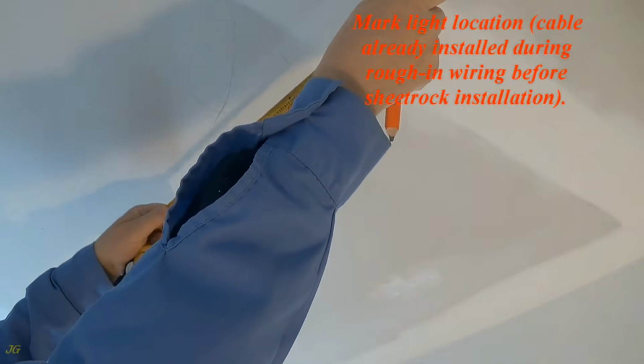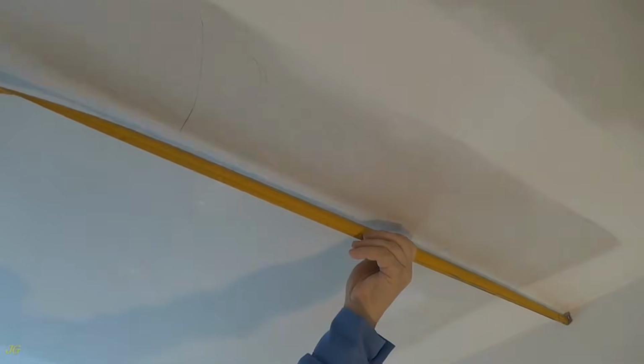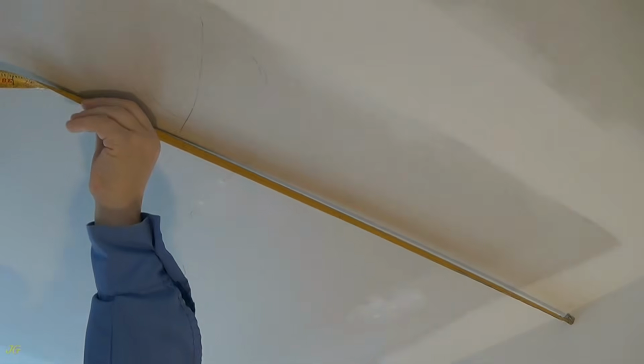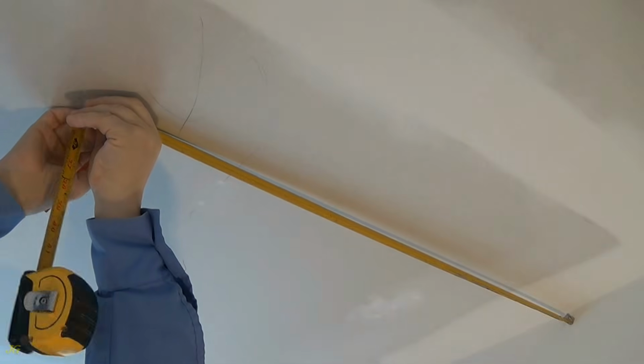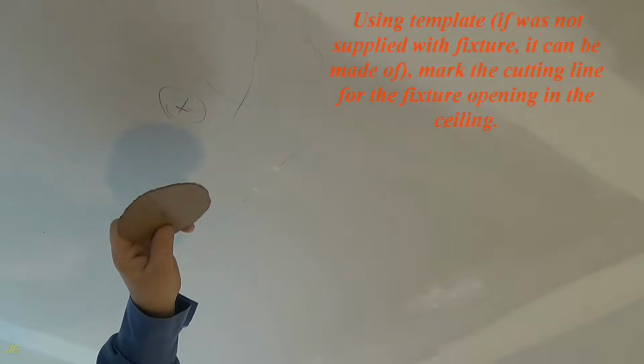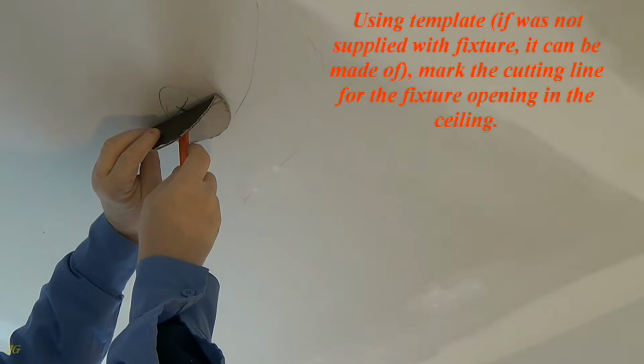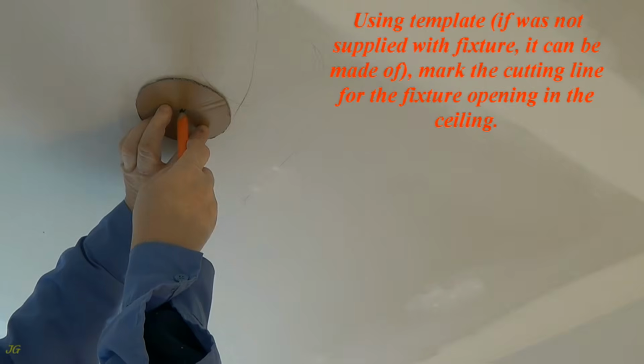Mark the light location, cable already installed during rough-in wiring before sheetrock installation. Use the template, and if one was not supplied with the fixture, it can be made. Mark the cutting line for the fixture opening in the ceiling.